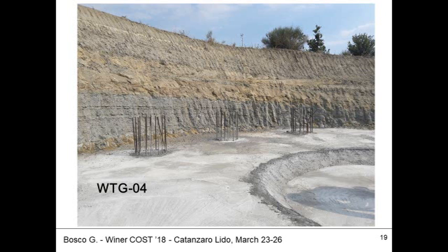Performing field testing in this material is essentially impossible, because when you hit this rock-like material, you will not advance. Drilling is the only possibility. Getting intact samples is impossible, because the thin tube will just buckle or bend, so you will not retrieve anything. So you cannot retrieve what is called undisturbed samples.